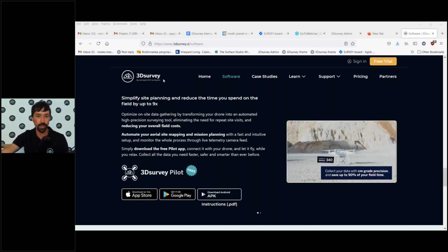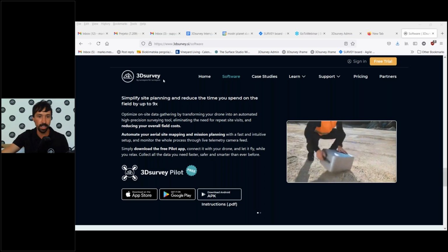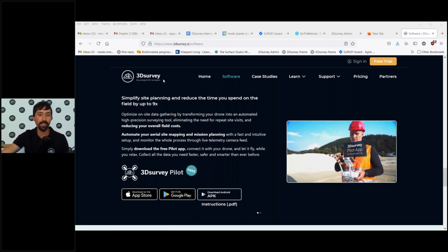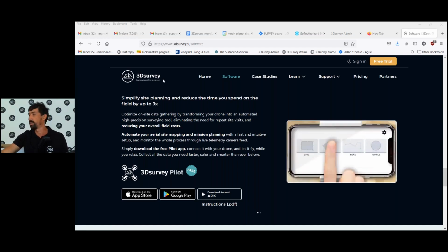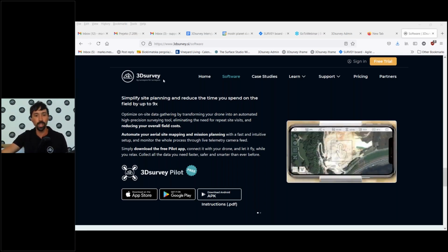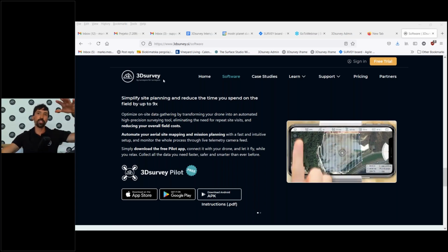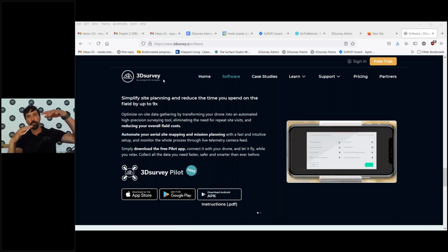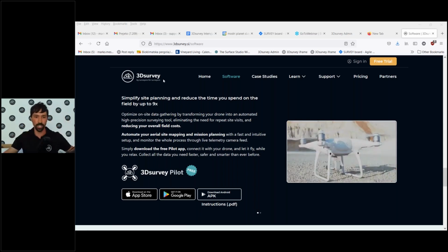Just going through the questions. Unfortunately, this platform doesn't have an option to show all the questions. Does a digital camera need to have GPS? No, there's no need. If you have drone images with GPS and digital images without GPS, they will be matched together, and the camera images will take over the positions from the drone images.